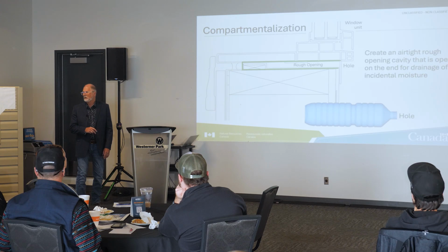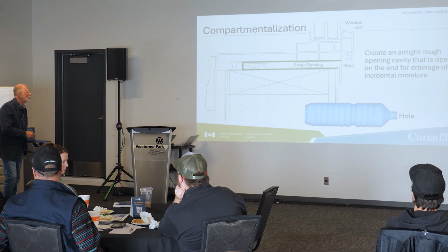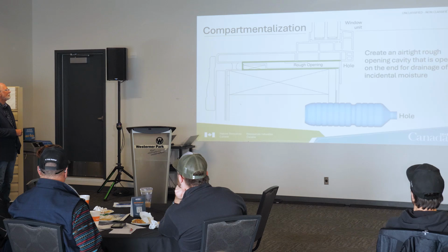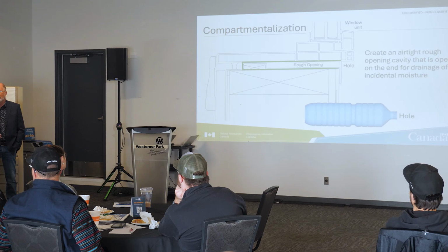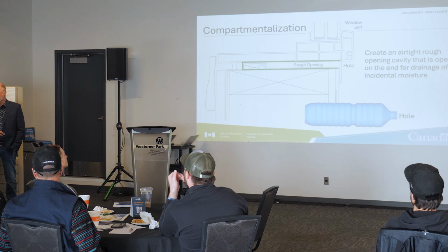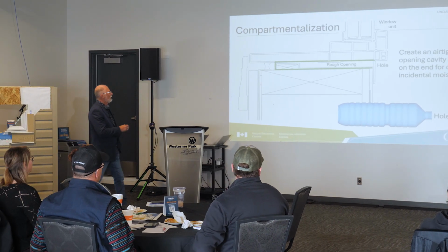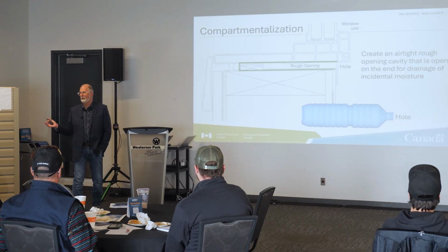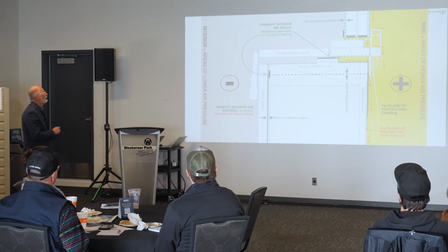I was just more wondering if it would change the R value at the point on the inside, because if air was flowing through that jamb extension, would your R value drop? Absolutely. That's the danger. Then also you have the potential of having condensation in here, which can still flow. Yeah. All right. Excellent point. That's why you do pre-drywall air tightness tests. That's why we recommend those.